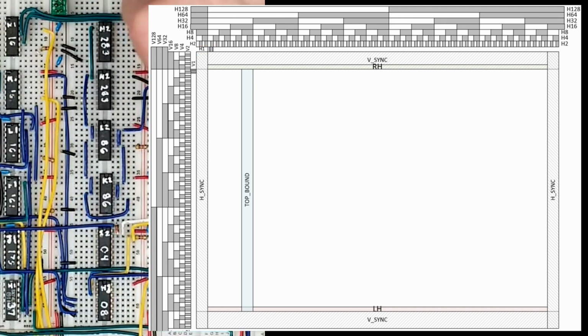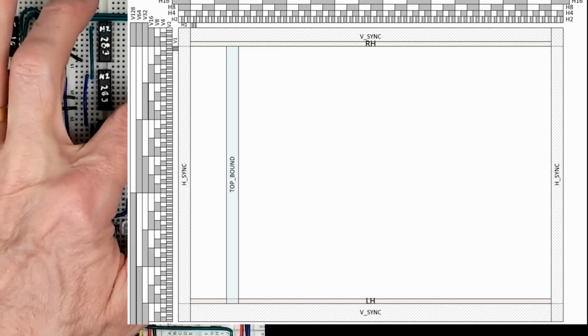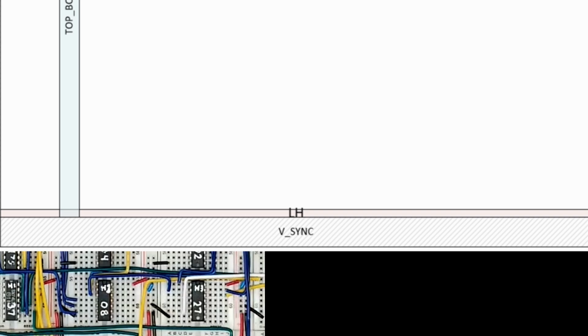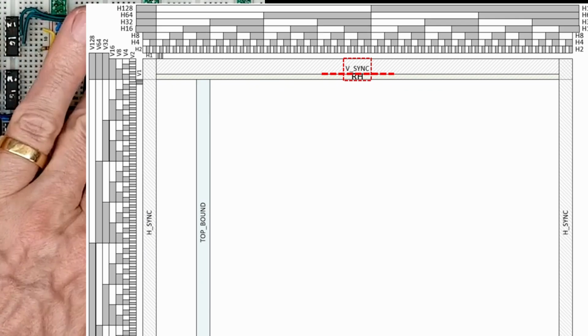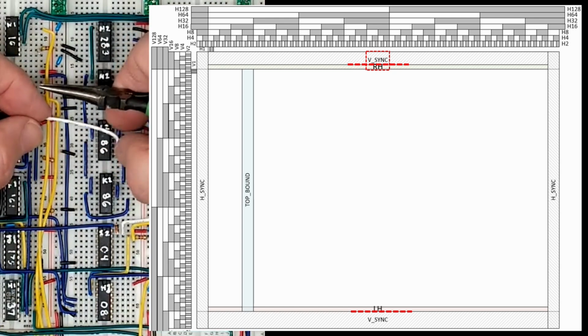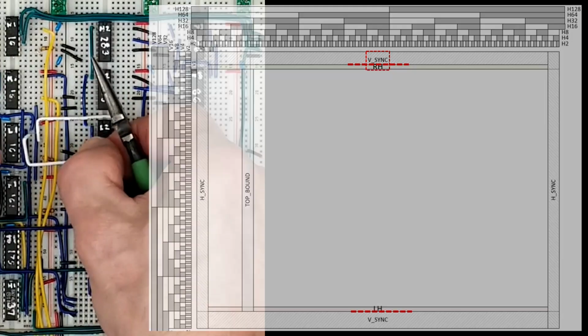We mentioned in the first part that the original prototype had many video issues. If you take a closer look at the drawings, you'll see that the left border is smack up against the beginning of VSync, and the right border actually sits within the end of VSync. There's supposed to be some good neighbor blanking before and after the syncs that's not observed. We call these blanking areas the front and back porches.